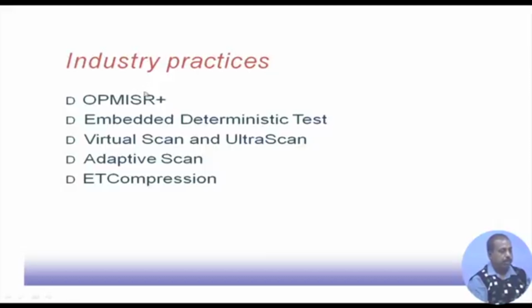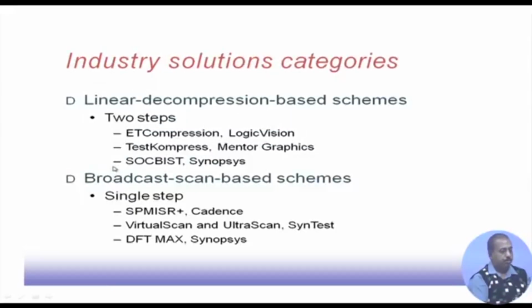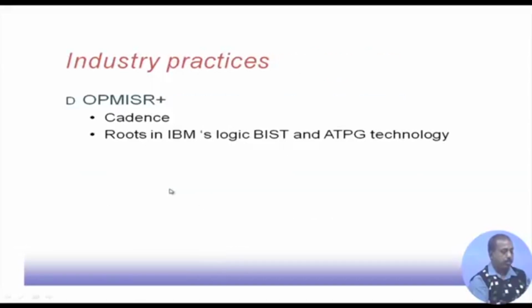There are several industry standards like OPMISR, embedded deterministic scan, virtual scan, adaptive scan, etc. Now, there are some schemes which are based on linear decompression, like ET compression, LogicVision, TestKompress from Mentor Graphics, SoC BIST, and the Synopsys tool. They are based on linear decompression. And then there are broadcast scan based schemes: OPMISR plus, the tool from Cadence, virtual scan, UltraScan, and DFT Max from Synopsys. They have broadcast scan based solutions.